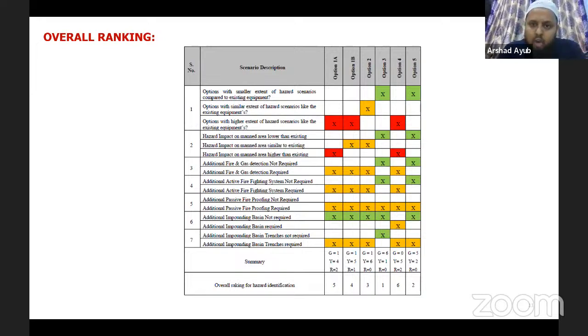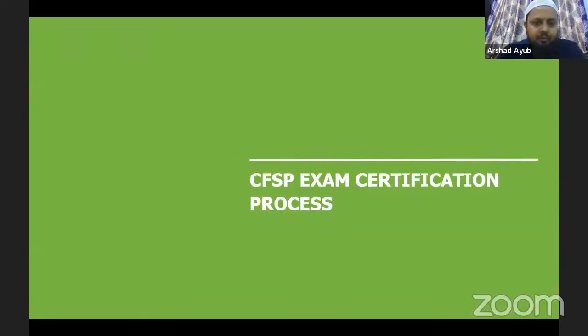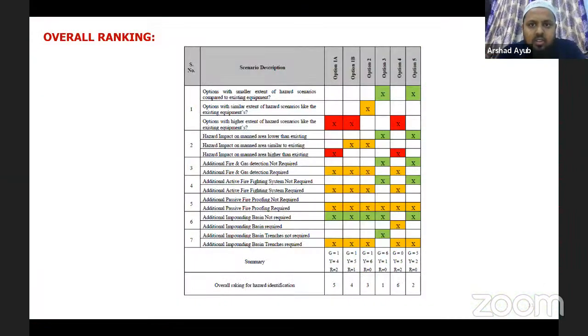Once you come up with a conclusion, then you start preparing the detailed layout. Then you go ahead with the typical HAZID, where we use the guide words, parameters, causes, consequences, safeguards for that particular option alone. Instead of doing HAZID for each option in detail, this way you can decide the better option and go. Once you decide, you can go ahead conducting the detailed HAZID for that particular option in the consequence stages. This finishes our hazard identification.